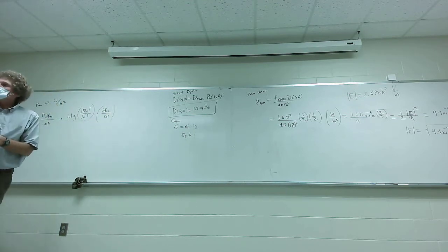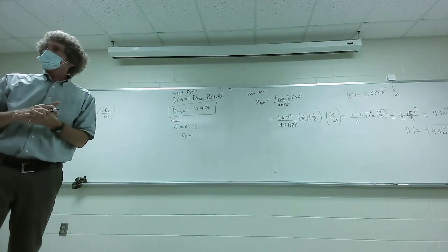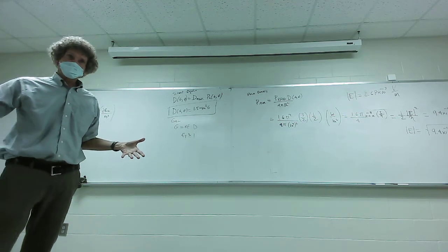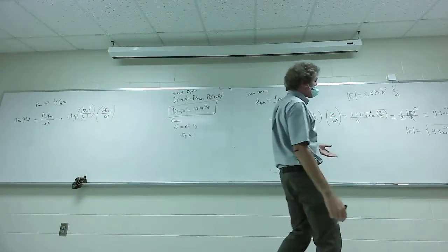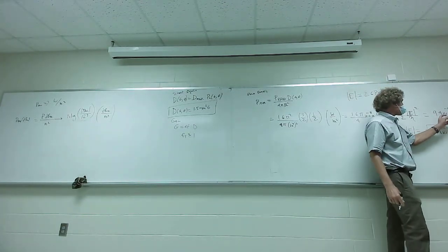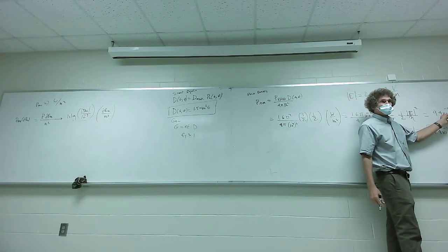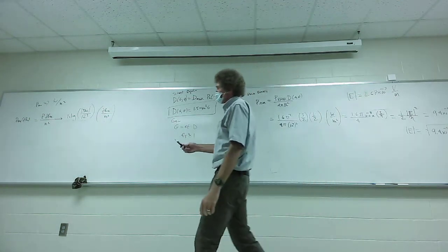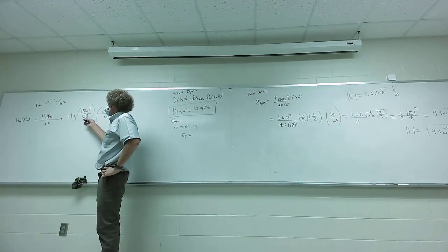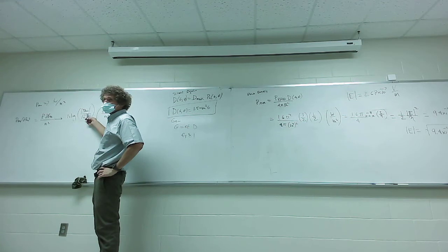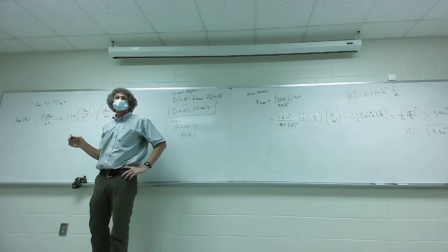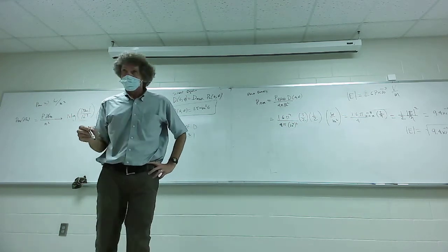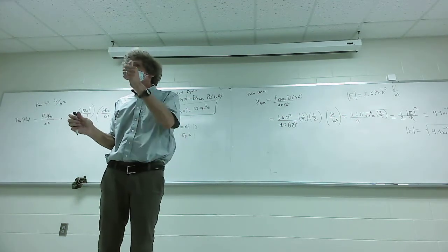Now, what you're going to see is that the dynamic range of values is condensed. That's the idea of using dBm. If we did this in dBm, call it 10 to the minus 8, approximately. If it's 10 to the minus 8, and we divide it by 10 to the minus 3, you have 10 to the minus 5. Do you not, class? Because the log of 10 to the minus 5 is minus 5. Minus 5 times 10 is minus 50 dBm per meter squared. Y'all follow me?